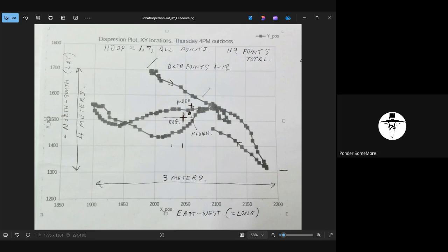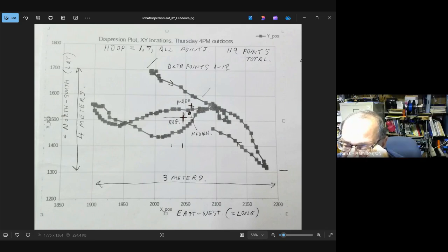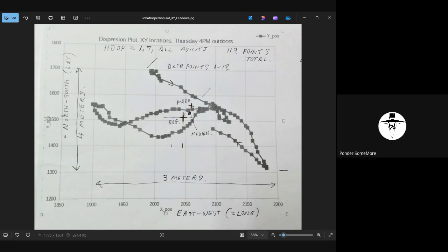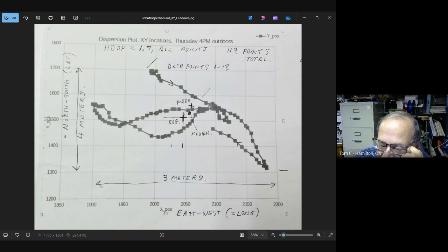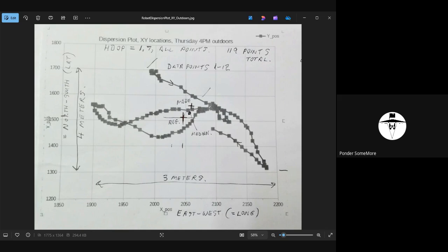Curiously enough, U-Blox said they made them thick so that you could put a tripod mounting screw through them without it coming out the other side. And you can get them with proper tripod mounting screws built in. But quite honestly, an aluminum pie plate, a throwaway pie plate, works for the purpose of a ground plane. It just needs to be conductive. Yeah. And it definitely needs to go outside of the boundary of the antenna's dimensions. Of course.